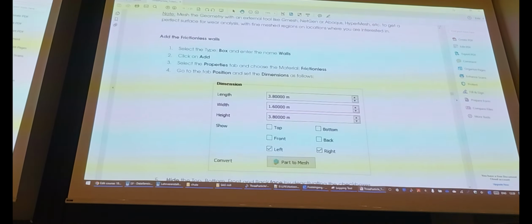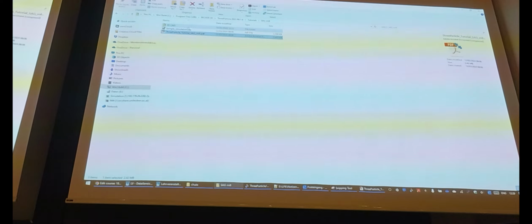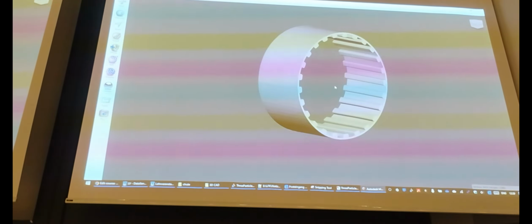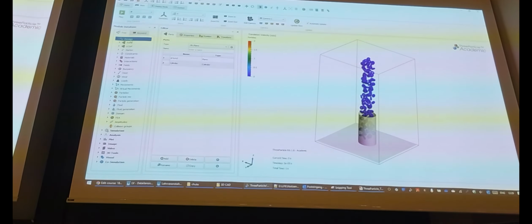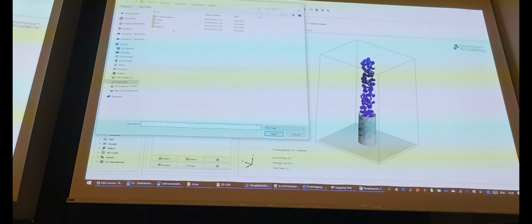And that's probably the last thing also in terms of complexity. If you have more complex things rather than planes, cylinders and boxes, you can just use 3D CAD files, for example, an STL file. That's an STL file. It's very simply opened with Windows. That's the segment from a CAD program, and you can import that directly in the program here. When you go to design parts, mesh, then it switches to import, and you can choose the file you want to import.